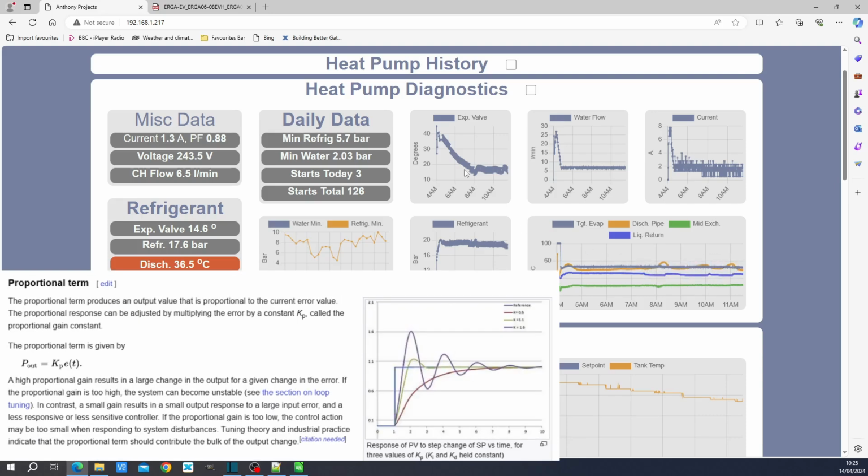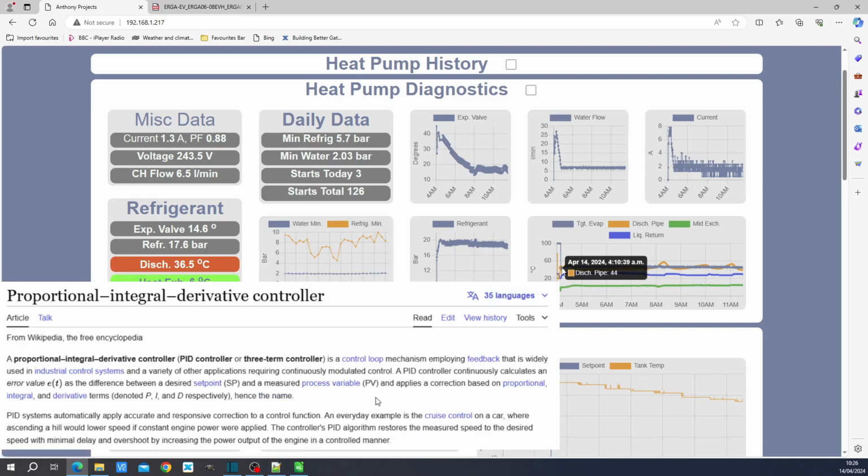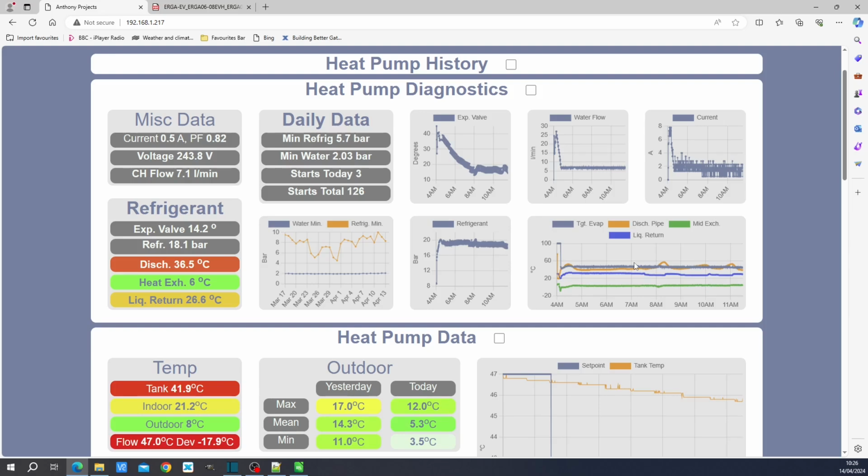And you'll also get instantaneous changes in the expansion valve position when the target temperature is changing very suddenly, for example. That's called proportional gain. Now, all three of those components, differential time constant, integration time constants, and proportional gain, that's what's known as a PID control algorithm. And you've got a lot of tuning which is needed to get all of that stable. But if your physical conditions are not stable, then your PID controller is going to be given a hard time.